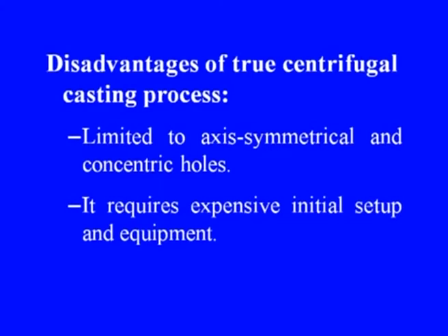What are the disadvantages then of the true centrifugal casting process? The process is limited to axisymmetrical shapes and concentric holes. It requires expensive initial setup and equipment.